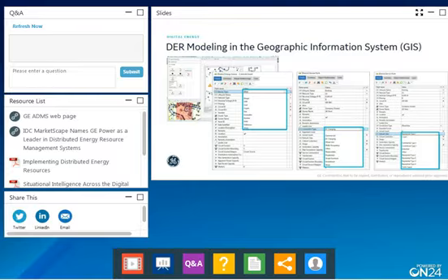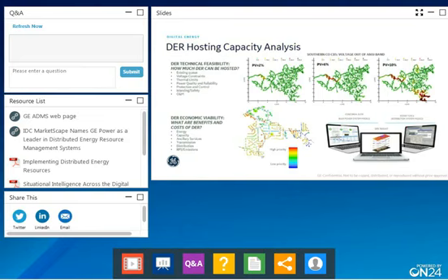And a whole range of very dynamic parameters, starting with the forecasting, the status, the dispatch capabilities that are left according to the contract, etc., etc. So you need to model the DERs right from the GIS, and it takes a lot more parameters than traditional assets. Then come the planning and hosting capacity analysis piece. Today, utilities have this traditional process to say, hey, here's a candidate load to connect on the grid. Can I accept it? Yes, no.